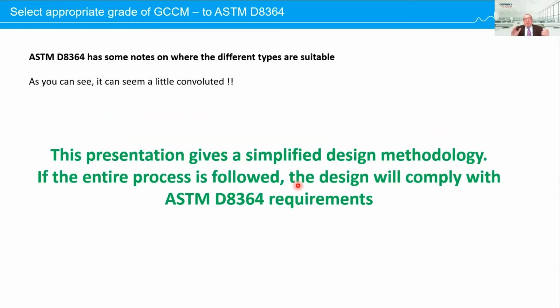Sorry to hit you with all that verbal from the standard, but as you can see, the standard seems a little convoluted, and the last thing I'd want to be doing as a designer is going through all that verbal description and trying to understand how to design a GCCM. So what I've done for you in this presentation is I've given a simplified design methodology. If you follow the entire process, the design will comply with the ASTM D8364 requirements.